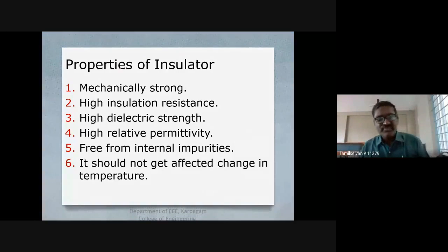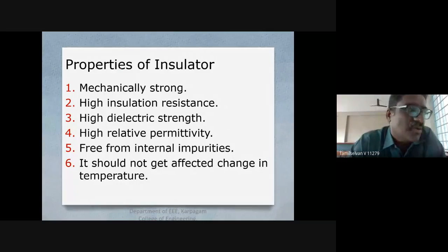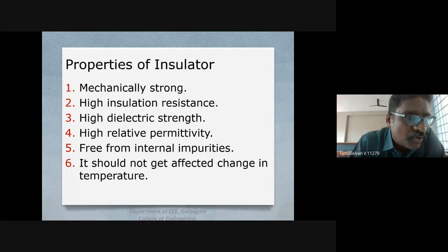The material satisfying these properties, and the most commonly used insulator, is porcelain. But we can use glass also, as a special combination material laminated to some extent with the insulators. Porcelain is produced by firing at high temperature a mixture of kaolin, feldspar, and quartz.